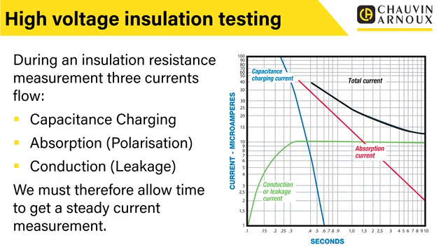We've also got what's called the absorption current, or the polarization current. This is a phenomenon that when you apply a DC test voltage, or a suitably high DC test voltage, to this dielectric, to this insulation, there is a certain current flow, and this takes time. This is the molecules within the insulation aligning themselves to the polarity of the test voltage.